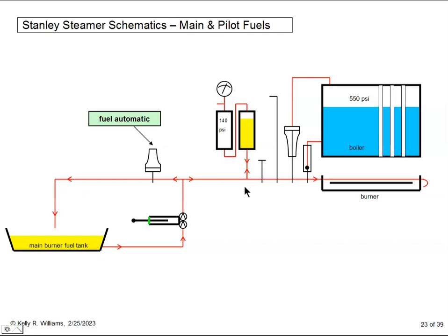When the pressure tank really comes into play, though, is during firing up. In this situation, the car is still, so the power pump isn't supplying any fuel to the burner. It all has to come out of the pressure tank. This only holds enough for a few minutes of fire, so there has to be a way to periodically refill it.